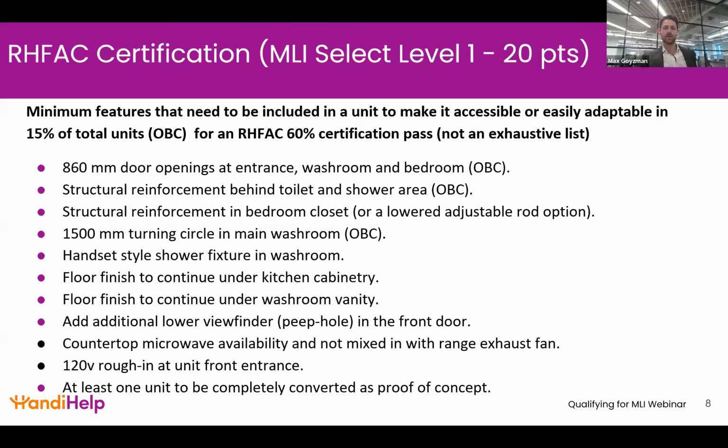Now this is going to be the Rick Hansen certification, but is this a review of the first time around, or have there been changes as well to the Rick Hansen certification? This is for the most part a review of last time. So these requirements are what is going to be overlaid onto the OBC units. It's not an exhaustive list, but it's the big items to sort of get your head around to start including: the wider doors, structural reinforcement, a 1500 millimeter turning circle, the type of shower fixture.